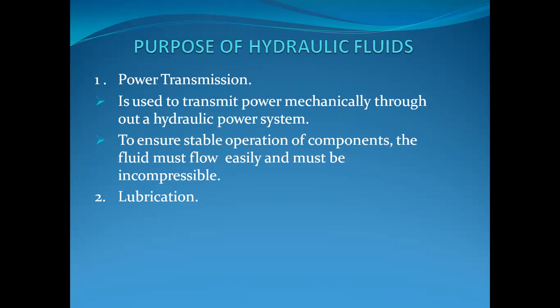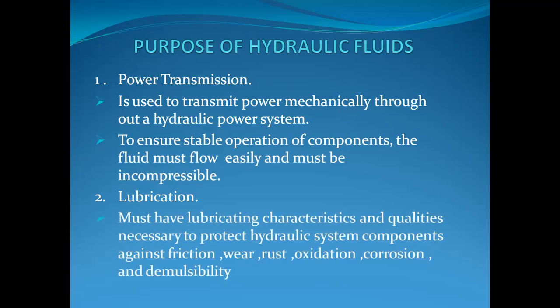And the second one is lubrication. We know that lubrication is the process of reducing friction, and the fluid must have lubricating characteristics and qualities necessary to protect hydraulic system components against friction, wear, rust, oxidation, corrosion, and demulsibility. We can explain all these terms.